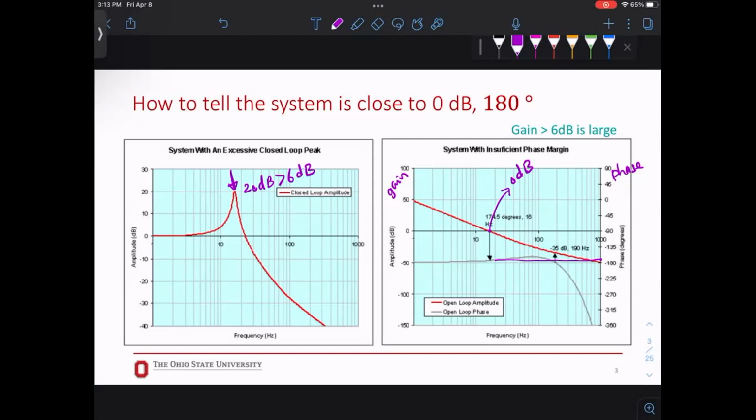Now, again, Dr. Z, what is so small? You're an engineer, you can't just use adjectives. So as a rule of thumb, as control engineers, we like to be above 30 degrees for phase margin, the amount that there's a difference. So if it is 30 degrees, we are good. So when you're designing a controller, when you look at the response in the Bode plot, measure that. And if it is 30 and above, you're good, right?